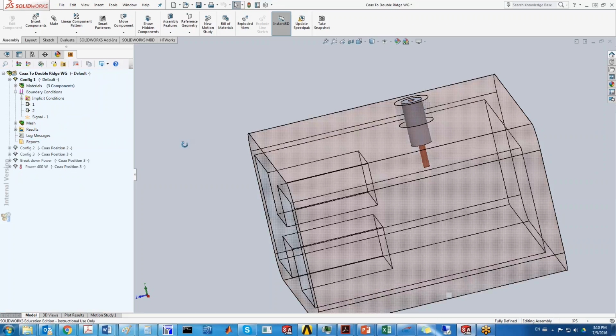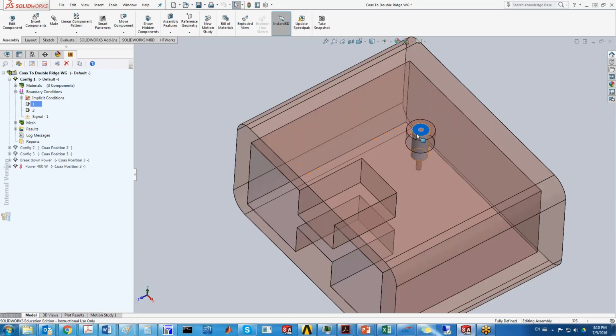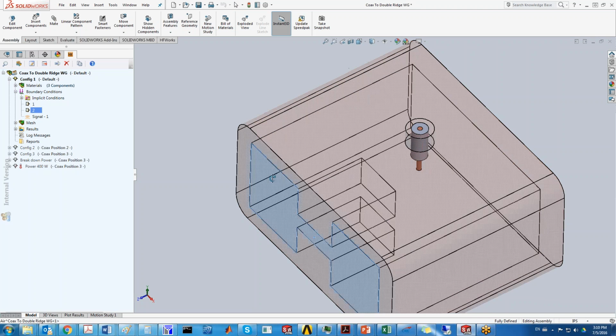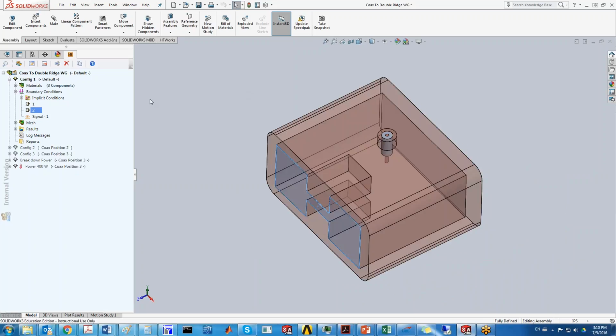So in this case, the key boundary conditions that I had to set is I have a first port, which is my entry port where the energy is going to come in, and this is my exit port, or this second port. The energy could also come in port 2 and come out of port 1. It's a fully symmetrical structure.